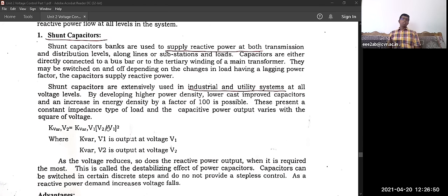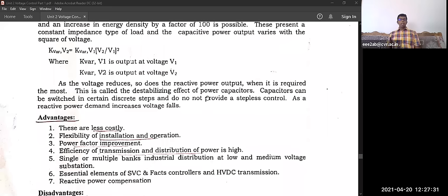That also. So for maintaining the shunt capacitor banks, whenever the power factor is lagging, they will simply switch on the shunt capacitor banks for some time, so that it comes to a constant value. And it may depend. Nowadays, due to modern technology, the feedback is also given automatically. It is switched on automatically. How many banks, how many capacitors they want to switch on, it is automatically switched on and switched off like that.